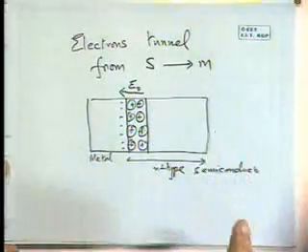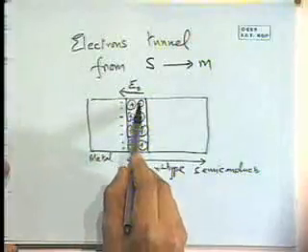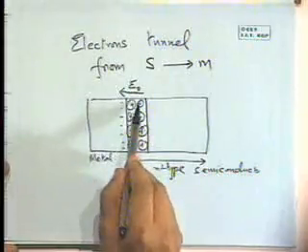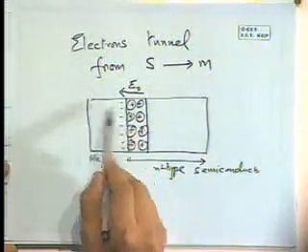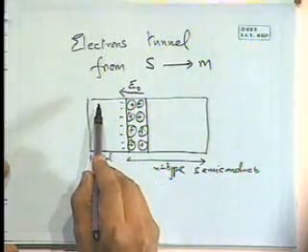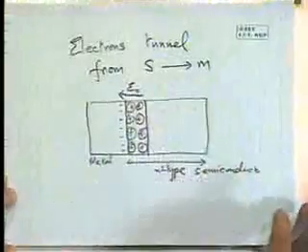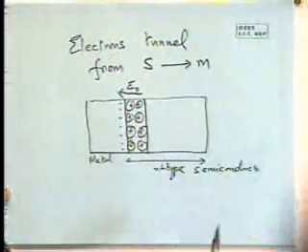So once equilibrium is established, equilibrium is being established because the field that is acting from this direction of the remaining positive charges towards the metal interface is able to balance out the field that is there, or the driving force that is there in terms of the energy difference between the electrons in both these materials. And at that point, the Fermi levels are equalized.